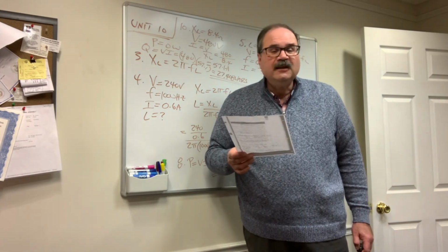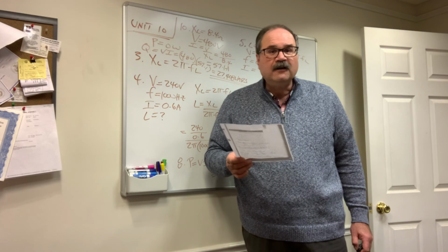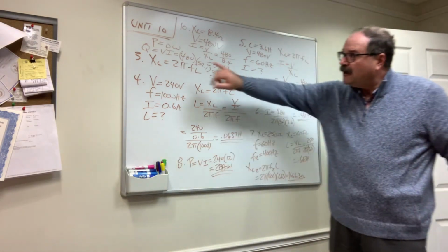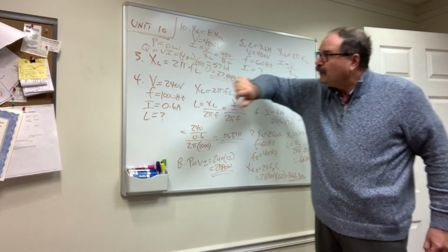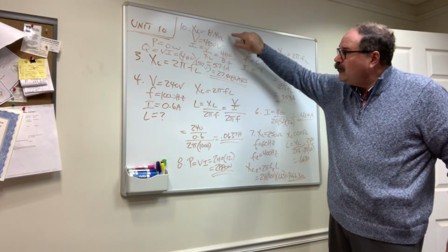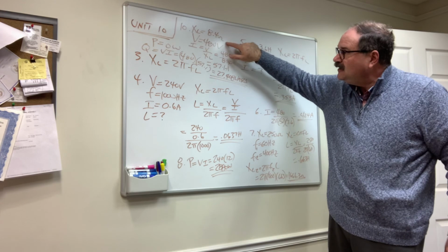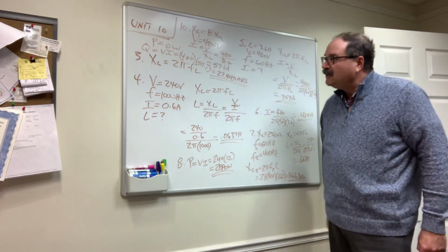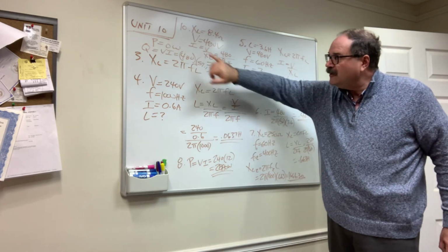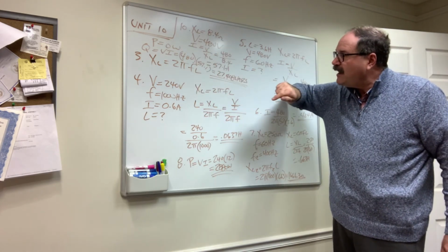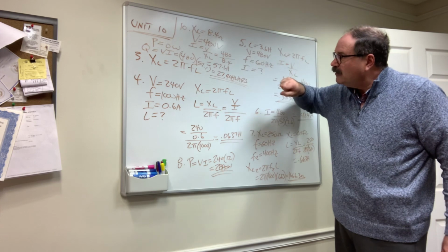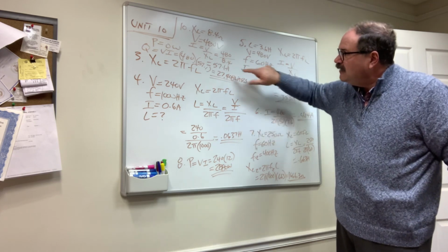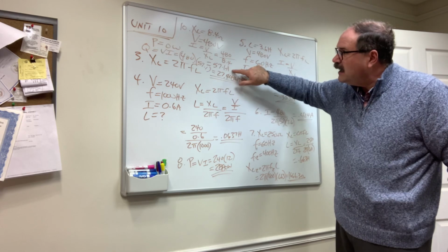So we're going to be solving for the value of VARs, volt amperes reactive. And normally VARs are represented by the letter Q. So again, put down what was given. Inductive reactance is 8.4 ohms. Voltage is 480 volts. We want to solve for current. So the current I is going to be equal to V divided by X sub L. Plug the numbers in. 480 divided by 8.4 is going to give us 57.1 amps.